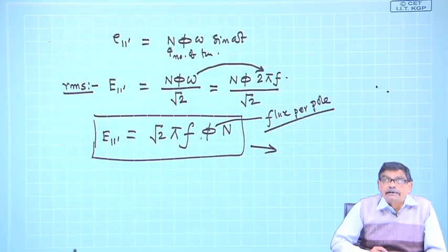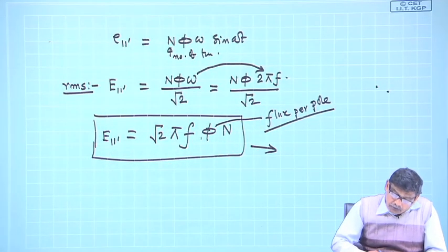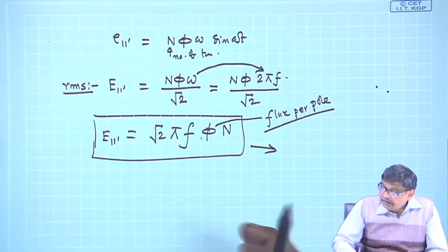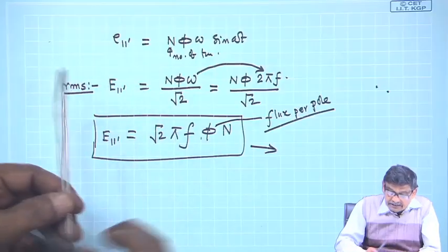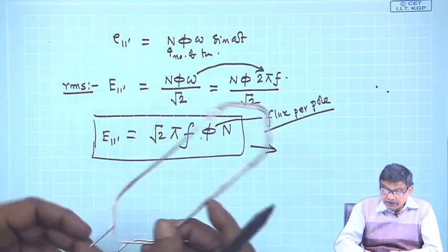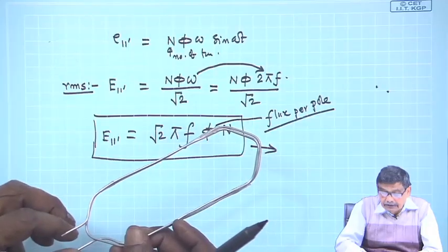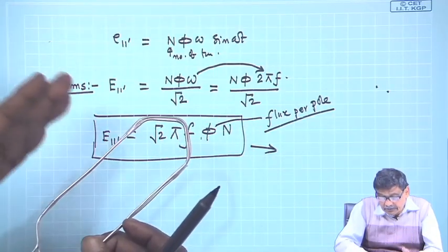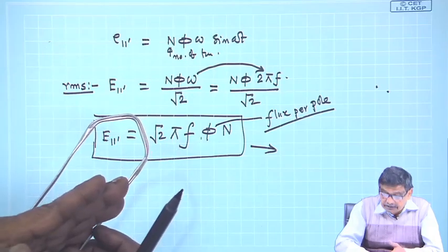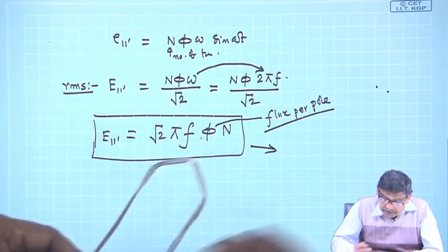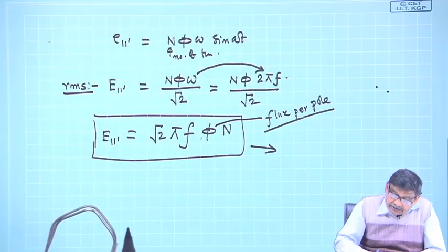You want to generate AC voltage. So, having n number of turns means this coil is having n turns and they are placed in appropriate slots, so that you maximize the induced voltage. That means that one coil side, if it is under the center of north pole, other must be placed under south pole, and they will be moving with constant velocity.